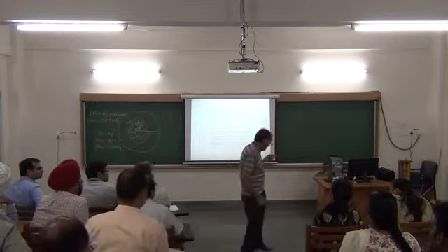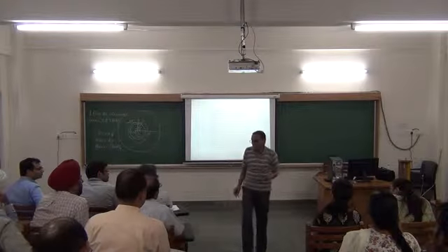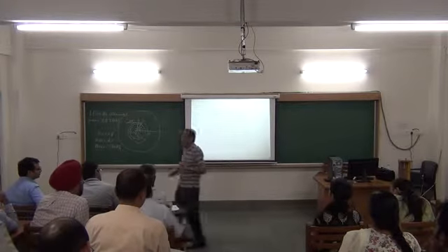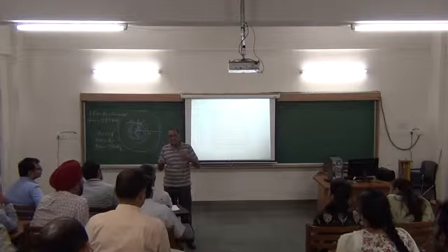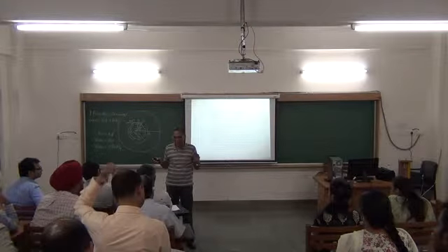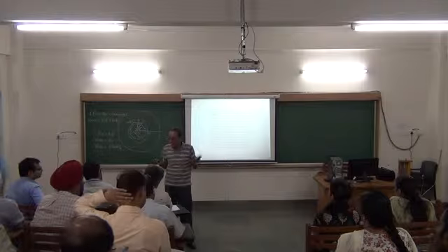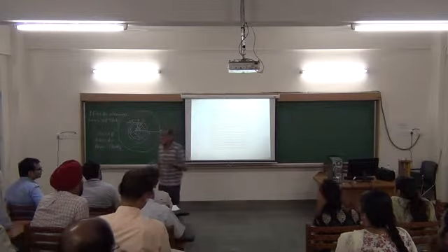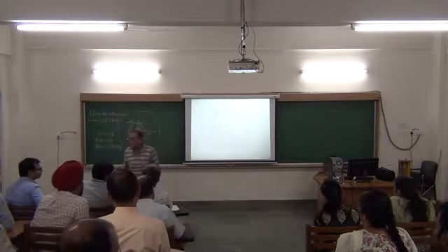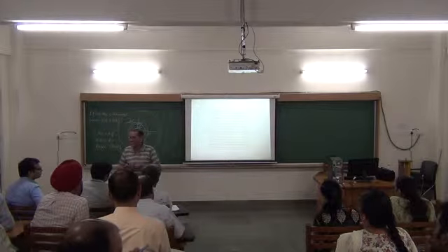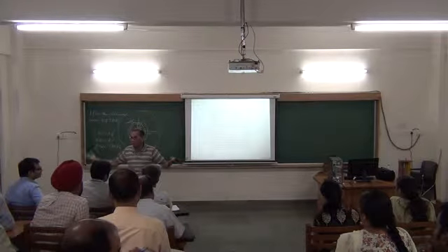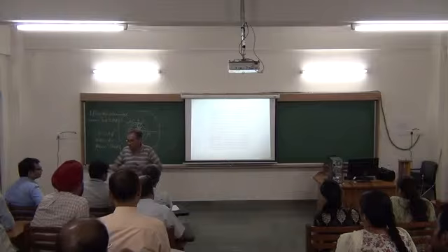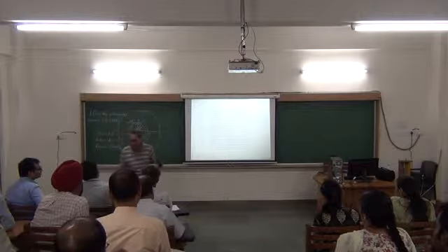So from this rigidity modulus and the Young's modulus of the bar, you can calculate some Poisson's ratio, but it won't be correct because the measurement is not based on the same material. Brass is a name given to alloys with a wide range of composition.